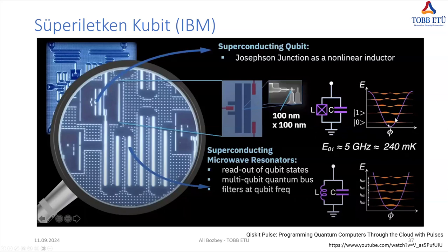That's why you can operate photonic quantum circuits at room temperature, because they operate at much higher frequencies, and their energy is above room temperature. So if you operate at 20 millikelvin, you operate maybe 10 times lower than the thermal noise, which is okay. And you cannot operate them at much higher temperatures.